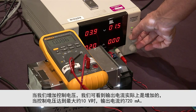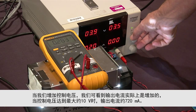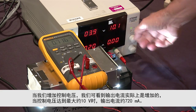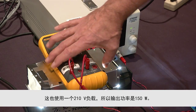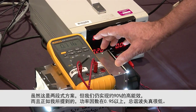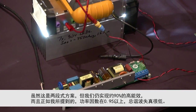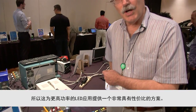As we increase the control voltage, we can see that the output current is in fact increasing. And when we reach a maximum of about 10 volts, we're running at about 720 milliamps. And again, this is with a 210 volt load. So we're outputting at about 150 watts. Even though this is a two-stage solution, we're still achieving about 90% efficiency, along with, as I mentioned, power factor above 0.95 and a very low THD. So this provides a very cost-effective solution for higher powered LED applications.